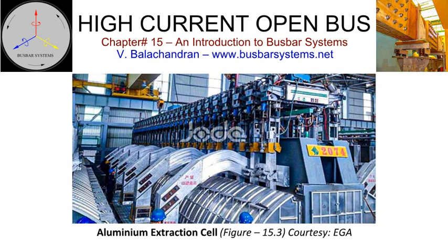Metal extraction plants are extremely power-intensive. Almost 1/3 of the cost of aluminium ingots can be attributed to the power consumption. With a pot line that is 1 kilometer long with 1,000 bolted joints, the efficiency, power loss, of the connection is of great importance. The voltage drop has to be limited to the extent practically feasible. The onward and return conductors are made of cast aluminium bars with a typical cross-section size of 200 mm, 8 inches, thickness by 600 mm, 24 inches, width.